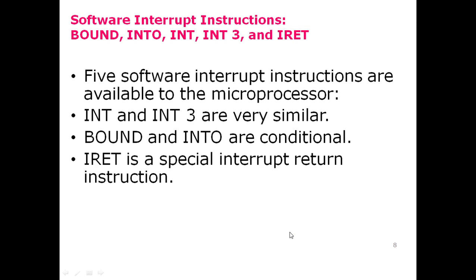Okay, so software interrupt instructions, the same instructions but in a little more detail. So 5 software interrupt instructions are available to the microprocessor, and INT and INT3 are very similar. INT is a 2-byte instruction, and INT3 is a special instance of this instruction, which is a 1-byte instruction. BOUND and INTO are conditional instructions. This checks for a value in the registers to be within the bounds, and this checks for the overflow flag. IRET is a special interrupt return instruction.